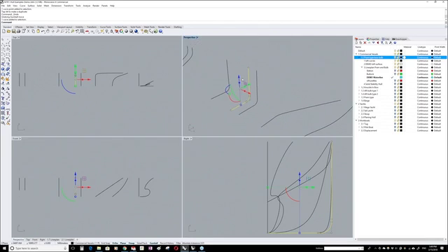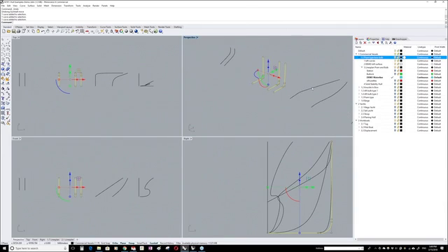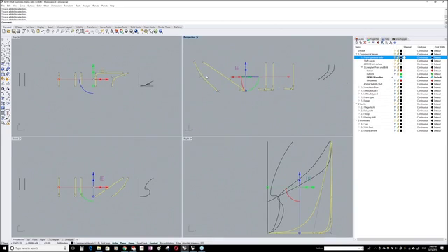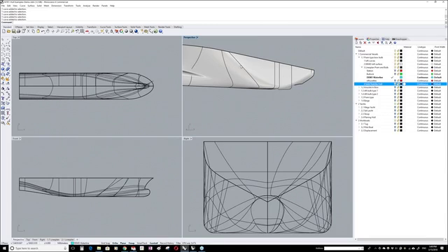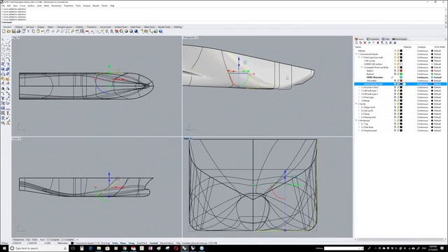So it's the same for the surface, because all the loft curves do have control points. And here, for example, let's have a look at one more curve. So here the surface is curved. Let's put the stability hull on here. So here the surface is curved, and here we want the parallel midship. So this curve has points that are already on the breadth of the ship. It's the first point at that breadth, and then the second point is on that curve and that curve. So 1, 2, 3, and then it is completely straight. Here it still looks straight, but mathematically it is not. So this is one important rule for control points we also use for loft curves.